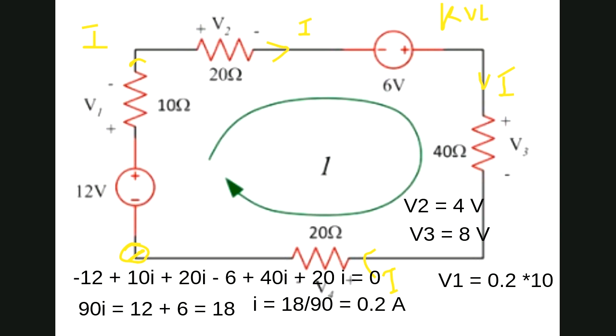So this is the way you can calculate. Once again, I'm telling you how to solve this. If you get a question in which voltage and all the resistors are given, and you have to find out the voltage across all the resistors one by one, what you will do at first is find out how much is the current. Then the voltage will be current into resistance. This is the way you can calculate. I hope it is clear. Any question, all of you? Anybody is having any questions?